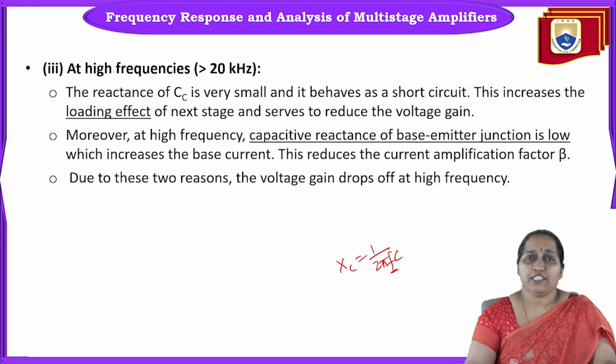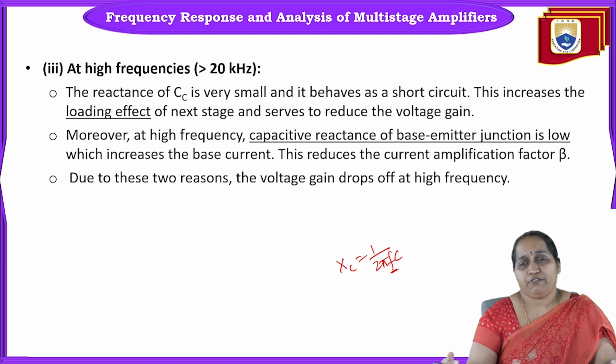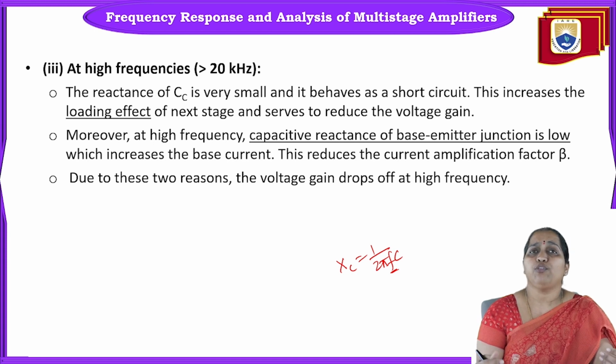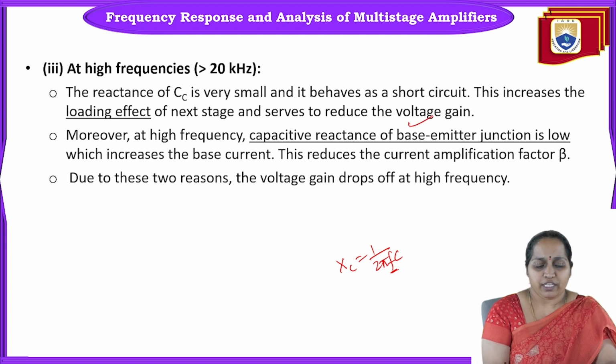Even in mid frequencies itself, we have seen that when the coupling capacitor is offering low reactance, the loading effect was more on the first stage. Now if you are directly replacing the coupling capacitor by a short circuit, still the loading effect on the first stage will be more. Okay, this loading effect on the stage will be more, and as a result the gain will be reduced. That is one reason.